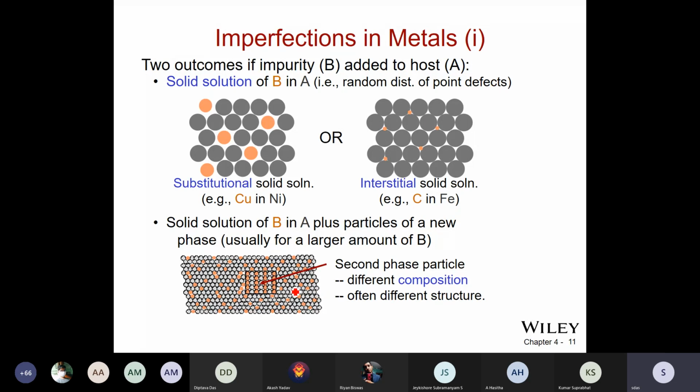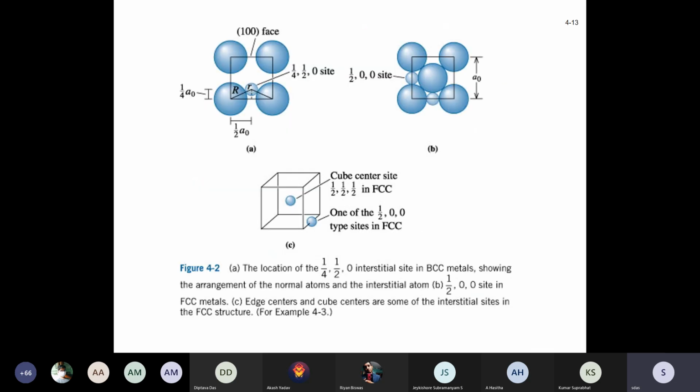Okay. Yesterday, Professor Mandal, when he was talking about small second phase precipitates. You look at an aluminium body of a plane or the aluminium utensils you have at home. It is basically aluminium copper alloys, 4.5% copper in it is called duralumin. Plane body also has a few other alloying elements. So if you control it, you heat it and cool it, it forms fine second phase particles. They are called precipitates. That gives the strength to this material. I will not go through it, and these interstitial sites I have already covered in crystal structure.